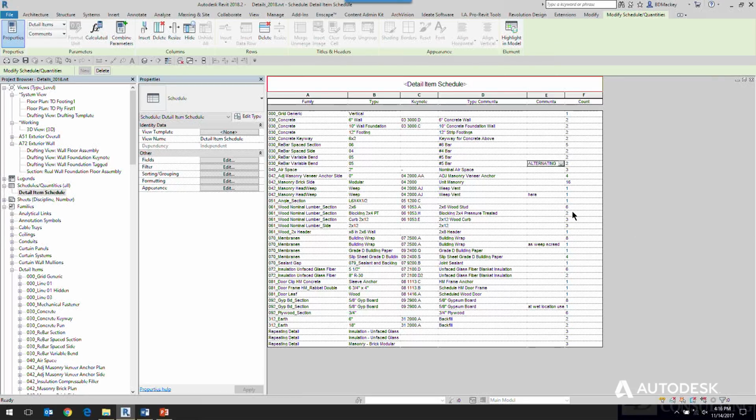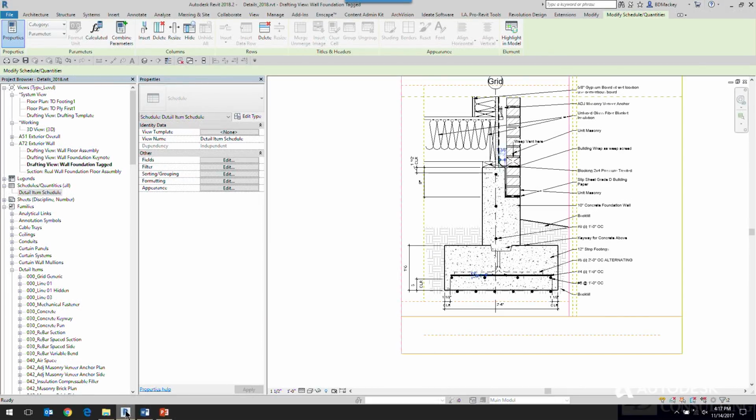Okay. So that's the last thing about the detailing: use that schedule to verify what's going on. Also, this is my other tip. You cannot spell check comments or type comments in Revit, but you can export this out to Excel if you have some sort of add-on utility. If you're using Dynamo, BIMlink, Pro Revit tools, whatever, export it to Excel, spell check it in Excel, and re-import it back in. That's your spell check. It's not the best solution, but you actually can do spell checking if you're exporting information out.